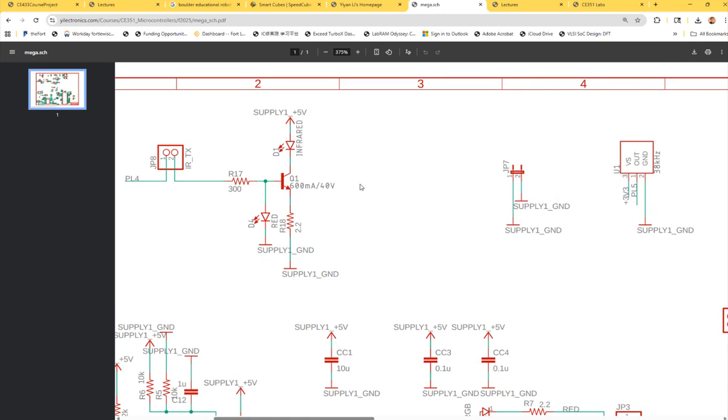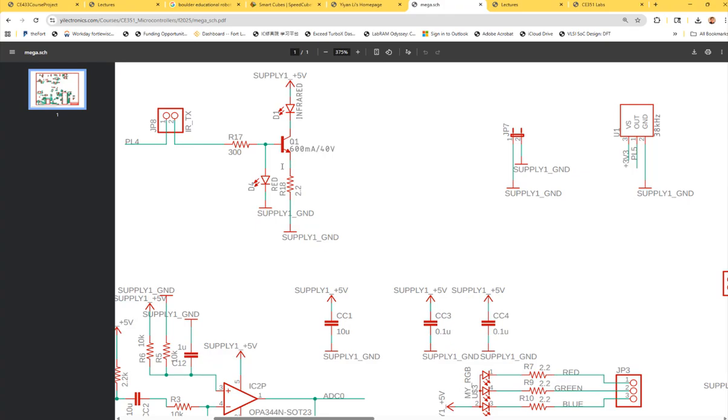You could also probe the emitter of the transistor and see if you can find pulses on the oscilloscope. If the pulses happen here, you know that kind of signal passes to your LED, so the LED must already have emitted something. Okay?